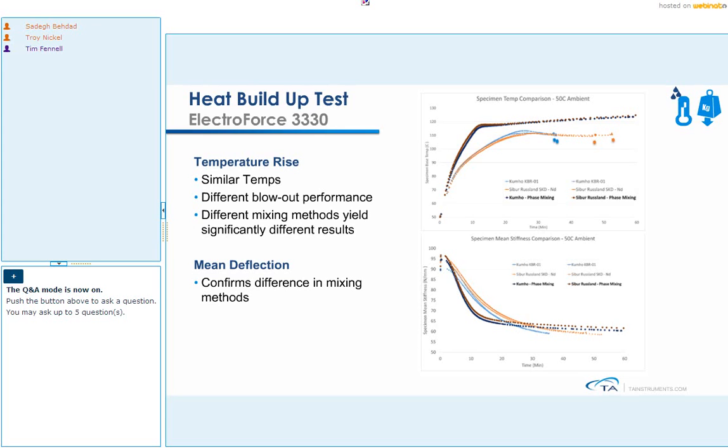Instead of creating master batches, if you do it the conventional way, because natural rubber and butadiene rubber have different viscosities and different wetting properties, you'll end up with a morphology where your carbon black goes to one phase more than the other. So you have this non-uniform distribution of the filler inside your molded rubber.